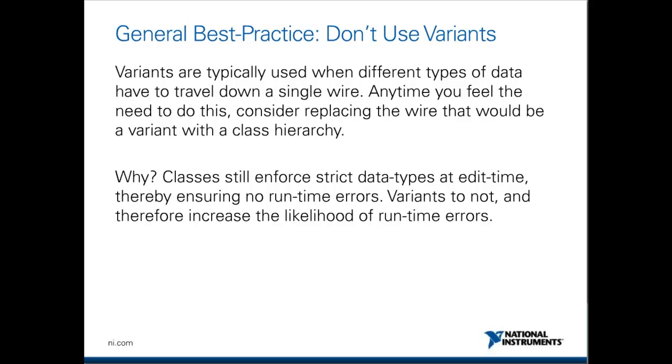Anyway, to summarize this section, one general best practice is that you want to avoid the use of variants. These are typically used when different data types have to travel down the same wire. And anytime you feel the need to do this, especially on a very large scale, consider replacing that wire with a class hierarchy. One of the biggest benefits is that classes will still enforce that strict data type that LabVIEW programmers are so used to, and it will enforce it at edit time, thereby ensuring that you won't have to wait until runtime to see erroneous behavior.